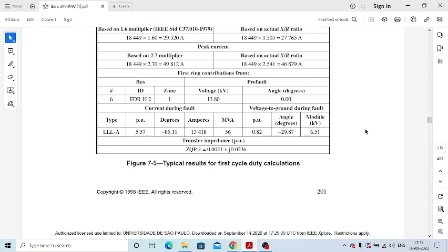But when power electronic based devices are largely integrated into the power system, the inertia is absent in the inverter based system. If a fault happens then, the fault magnitude contributed by inertia is also absent. That is one of the important concerns now.